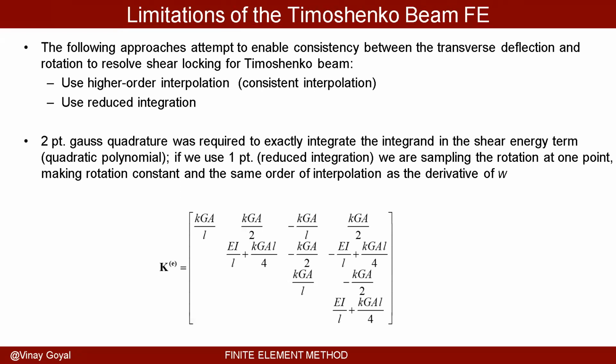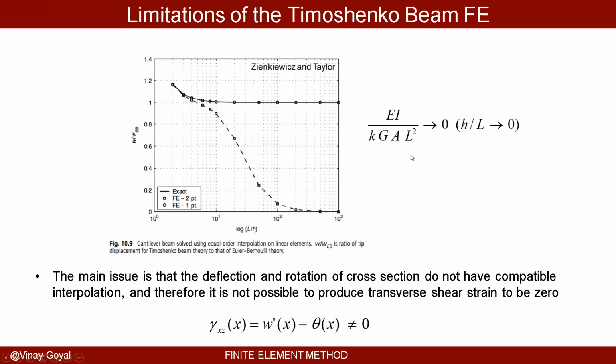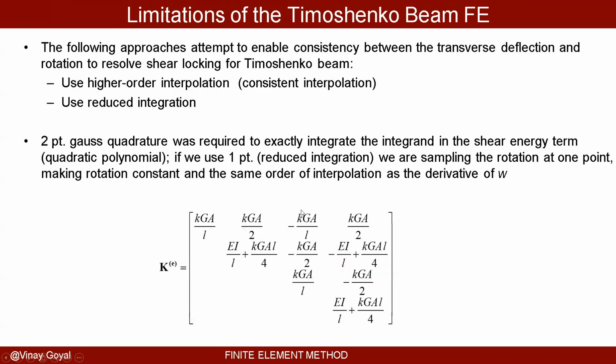So the following approaches have been used in the past to achieve a better solution. And this is called shear locking. This issue is called shear locking because it's locking the solution. It's not letting it bend. You can use a higher order interpolation. That's one solution, and I show you in my book how to do that.